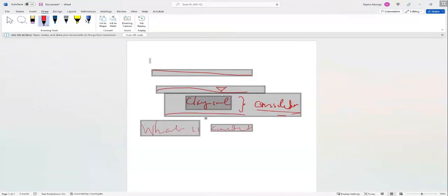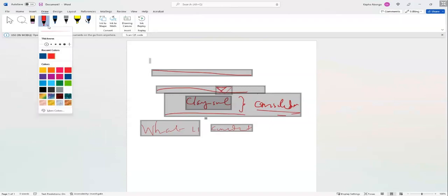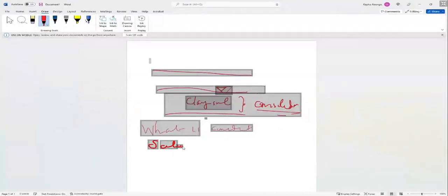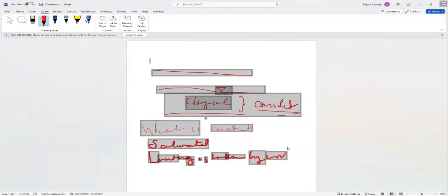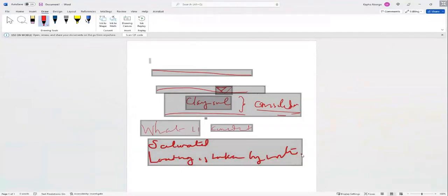Now, the consolidation occurs in fine-grained soil when you apply loading on that soil. The soil is saturated. Initially, the loading is taken by water. When you apply loading, it increases the pore water pressure.